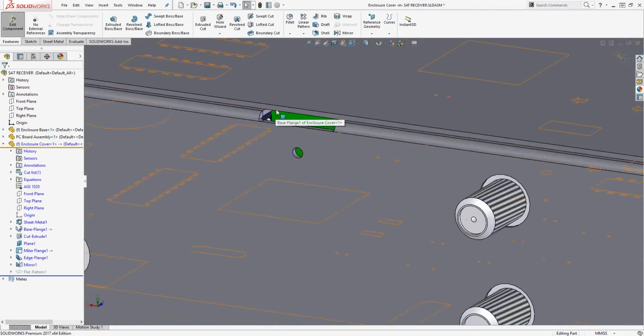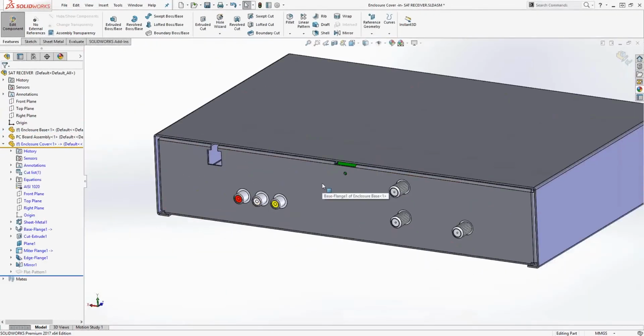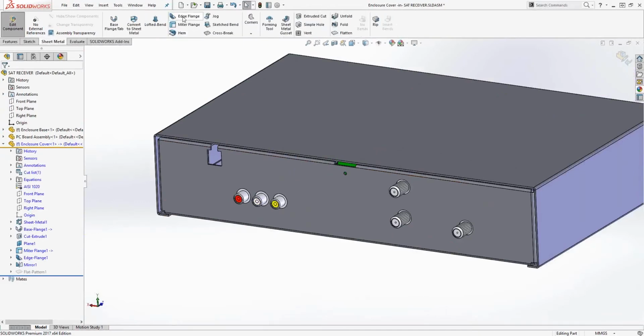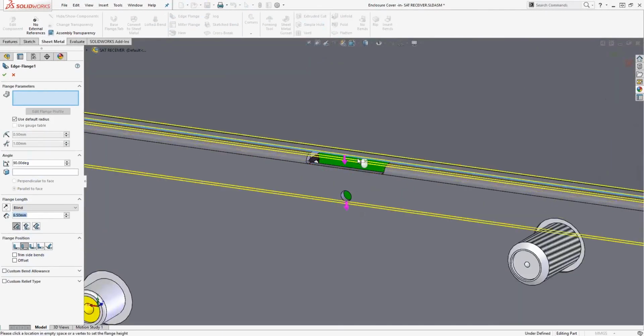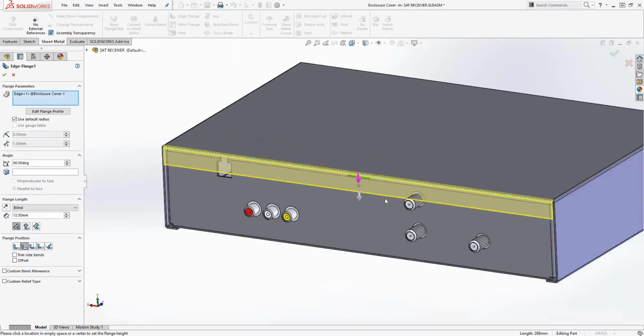Right, so we're going to create an edge flange that fits right there. You can screw this in, so we want to have a hole right there as well. So we'll go into our edge flange tool one more time. We'll go down like so. Now I showed editing the sketch after we create it. You can also edit it right here. And if you have multiple ones, you can choose which edge that you are editing, right?